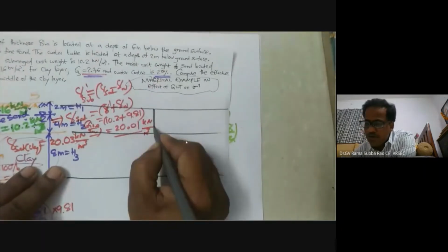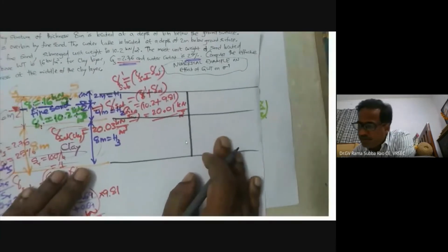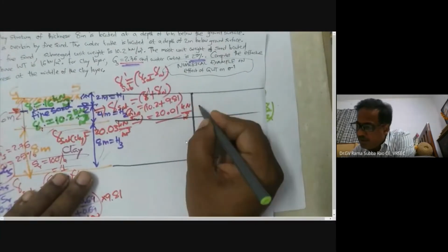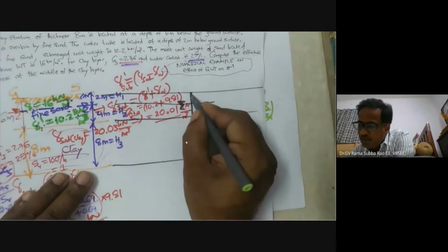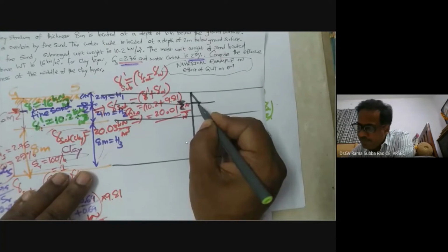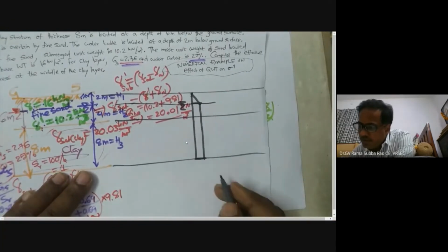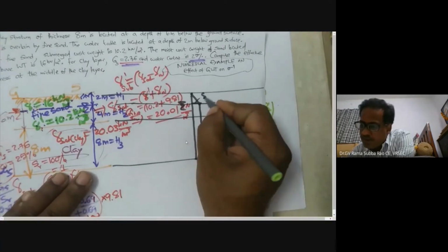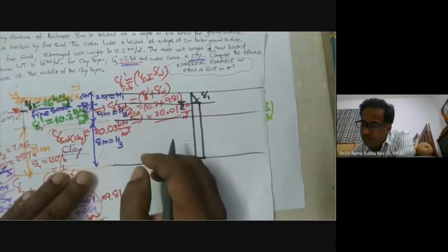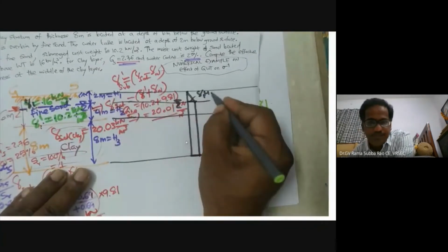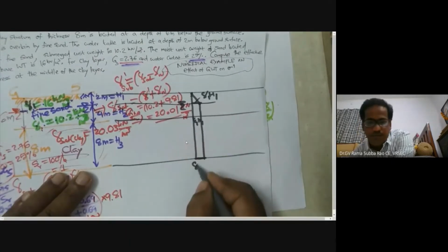Now I'm going to draw total stress. So let us see now. Yes, it is visible now. Yes, here you see we have one more. Actually, water table is here. Now you see this is gamma into H1. Then it is going to be constant. So now this I would like to write gamma 1. Otherwise, for your understanding, this is gamma 1 and this one is H1. Now gamma 1 H1.